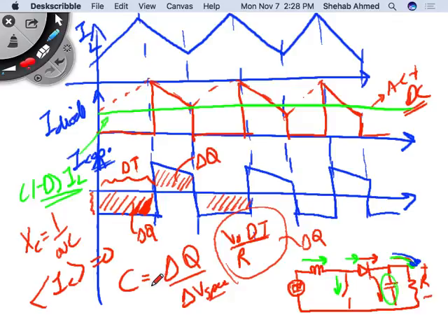But in reality, I have a resistor in series with the inductor. I have a resistor in series with this capacitance. I have a capacitance value that is plus or minus 20% of what I'm thinking it is, because that's what the data sheet tells you. So in reality, you will never be able to allow 100% of the ripple to go through. I don't know if I make sense or not.